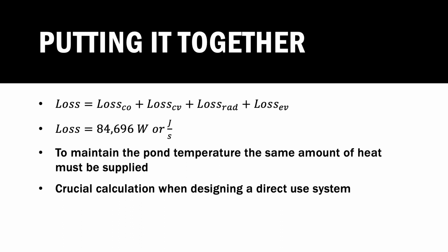This is effectively equal to the amount of heat energy that needs to be initially input into the system to maintain the necessary pond temperature. It is worth noting that the largest contributor to the heat loss in this problem is that from conduction. However, eventually, the ground on the other side of the concrete pond walls will reach a similar temperature to the pond water. This will in turn make the thermal gradient approach zero, and correspondingly the heat loss from conduction will become trivial altogether. This leaves evaporation as the largest contributor to heat loss in this system in the long run.